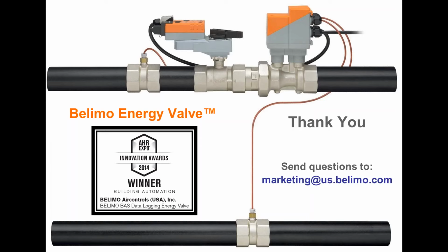Now, all Belimo catalogs contain a chart that will show you, let's say you buy that 2-inch valve, but you're only going to run it at 45 gallons a minute. Well, there's a chart in there that will tell you how much pressure is required to achieve 45 gallons a minute through that valve. So as you do your pump calculations, you're going to want to consider which valve is sort of your critical one, which one you're sizing your pump based on, and then take a look at the specific. But the short answer is if you size around 5 psi, you're done, but you can do a little better than that if you want to dig down into it.